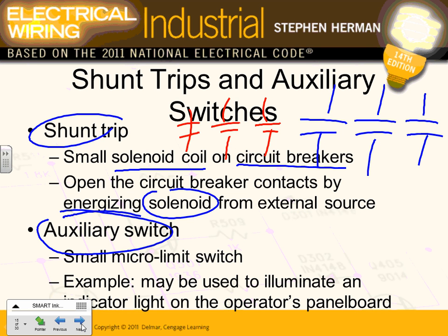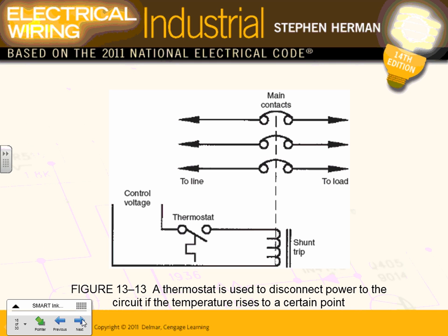So the smarter ones, the A guys, are going to write on their PDUs and crack units, provide shunt trip. That's it. Shunt trip. That's a function, a little function. Okay, here's how it looks. Very simple, very easy, guys.